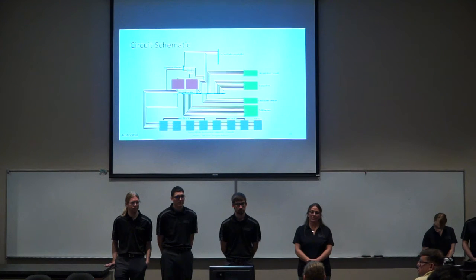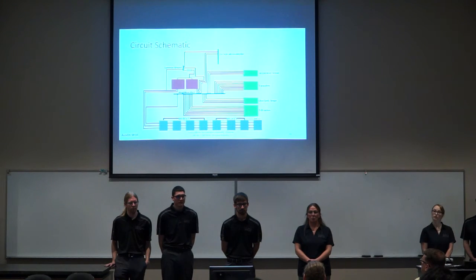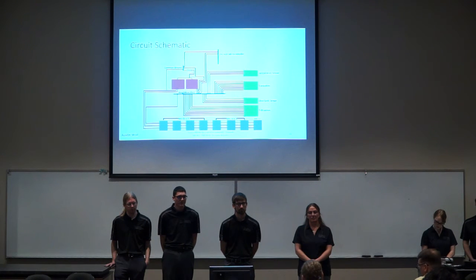The other thing is those components are not currently on your costing. You're going to need a number of additional components for the power regulator for the BeagleBone Black. You're going to need some additional components for the temperature sensor. I believe you're going to need some additional components for each of your three additional green blocks there. So at the moment, we cannot give you advice on whether it's going to function or not, because you haven't given us a complete schematic. So you've given us a theory, but not any ability to do a design review. Does that make sense? Yes.